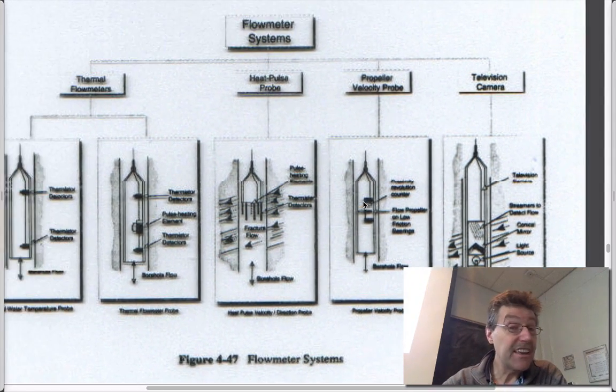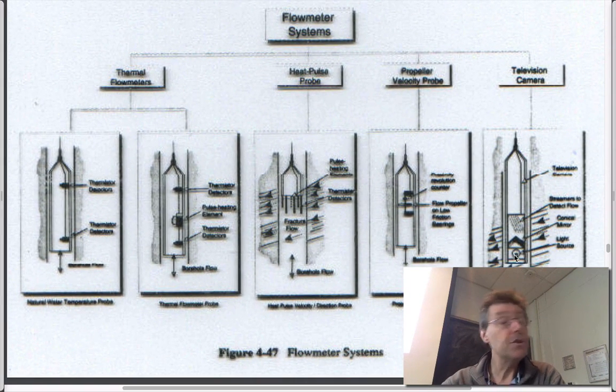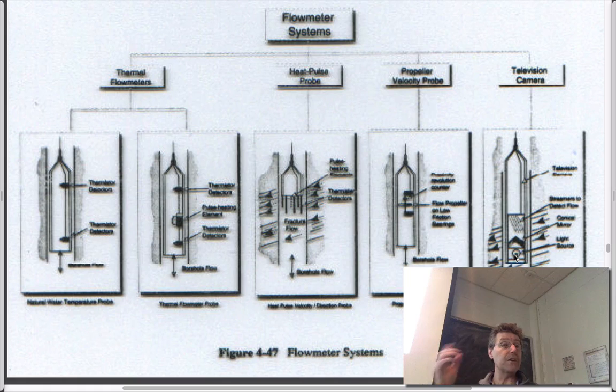More exotically than that, I've never ever seen these. Well, I have seen some of these. You can use borehole cameras. So you have an empty borehole. Maybe you didn't take core because you drilled it down really quickly with a rotary drill, just rammed it down, looked at some of the chips but don't have anything. What you could do is go in there after the fact with a borehole camera that just takes an image of the borehole as you go down, records it, it says exactly what's in there, and you get a stratigraphic log of exactly what's in there with time.